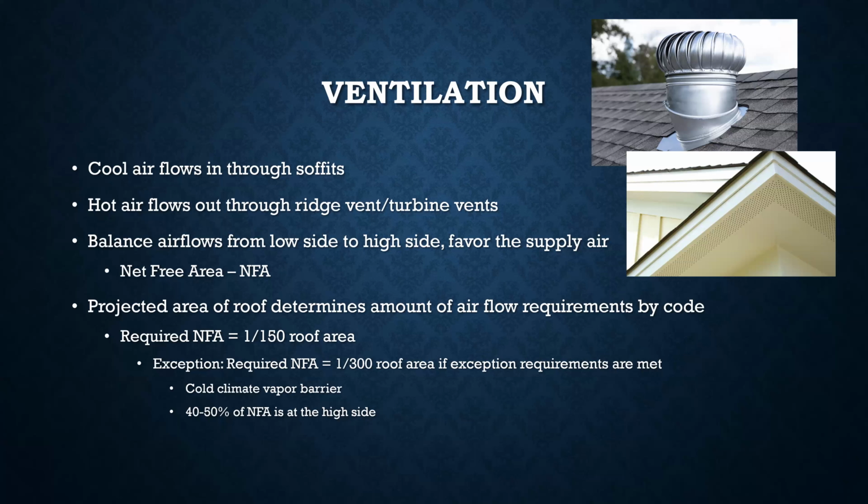The way we measure and account for that is what is called net free area. It's basically measuring how much total area you have for air to enter your attic and how much total area you have for air to exit your attic. I said in here that you want to favor the supply air, so you'd want more airflow getting into your attic than leaving your attic.